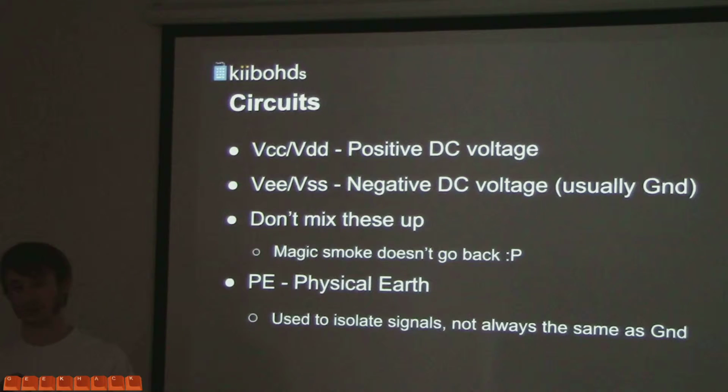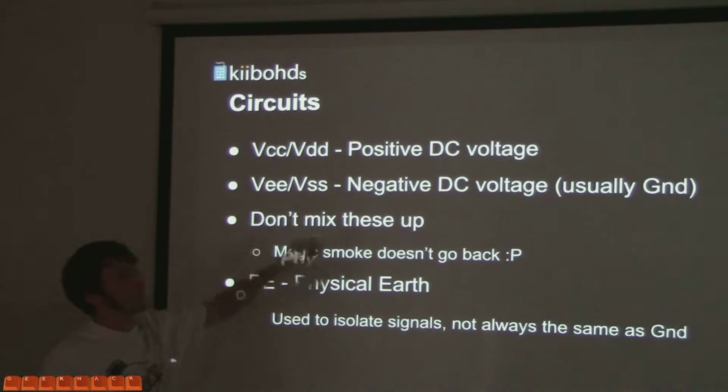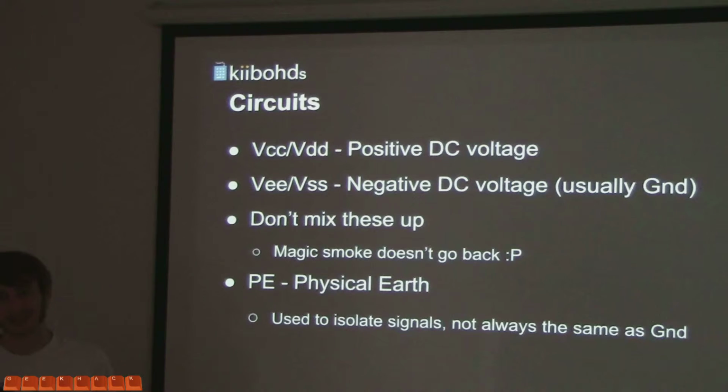So in this whole process, you're likely going to have to look at data sheets. And some labels of things are different depending on what kind of data sheet or what EE lingo they're using. First one, VCC, VDD, or V plus 5. That means positive voltage. VEE, I never see this one. But VSS or ground, that means typically ground.